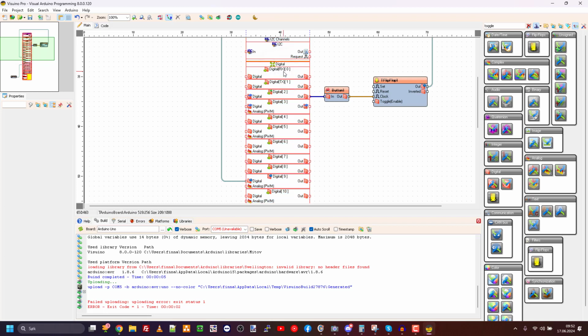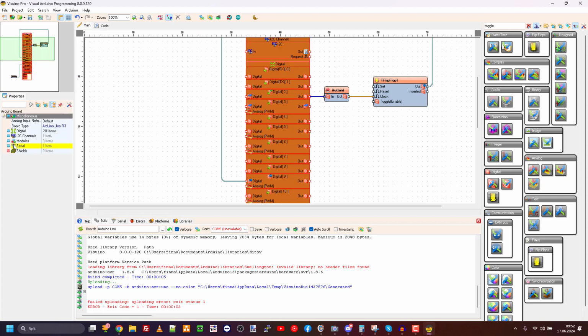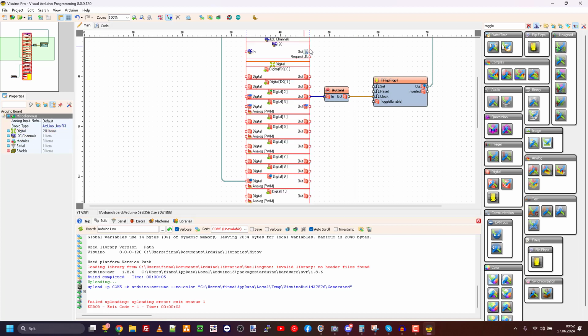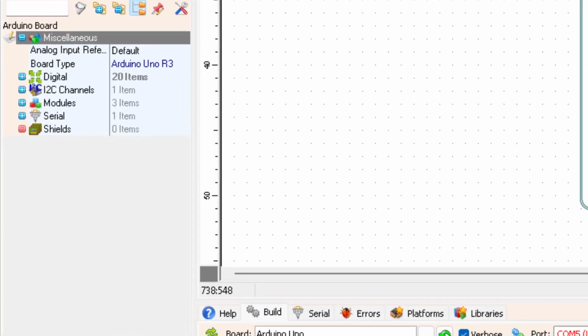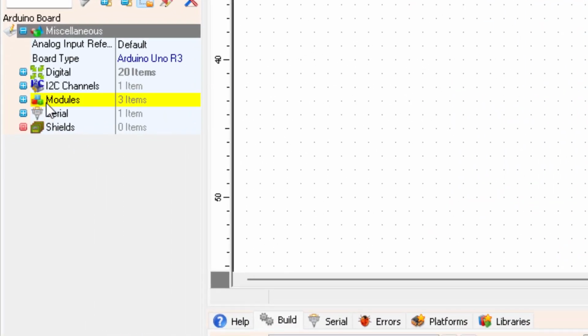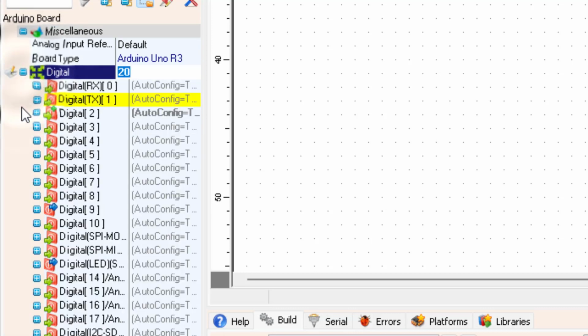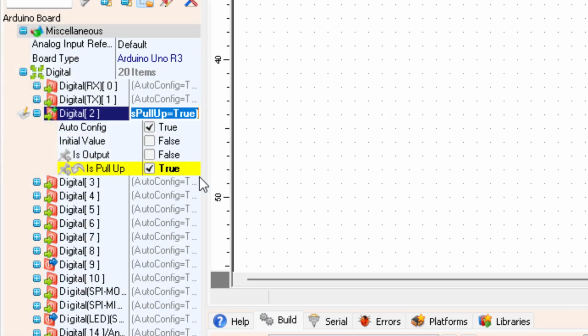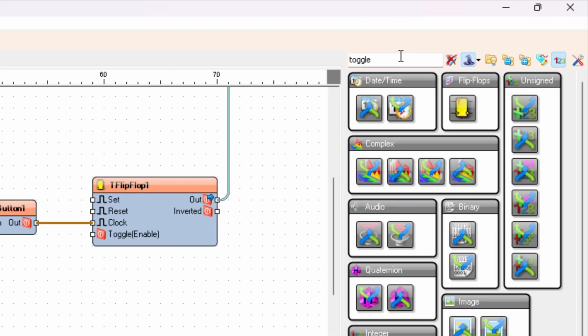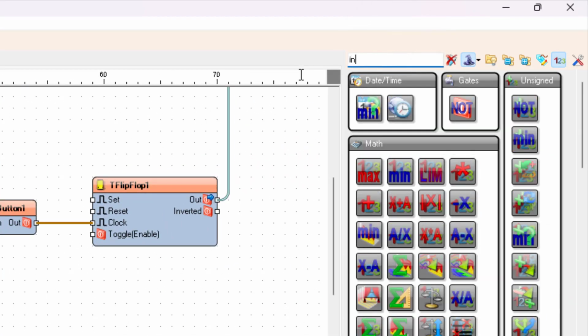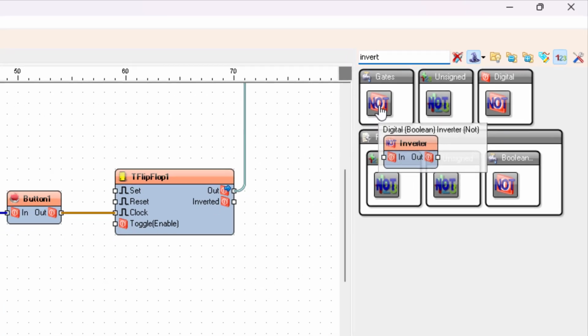We have forgotten that when we are using the pull-up resistor, we can check here again. When we're pulling that one up, then it will be held high when the button is not pressed. So here we need to invert that signal, since I did it this way.